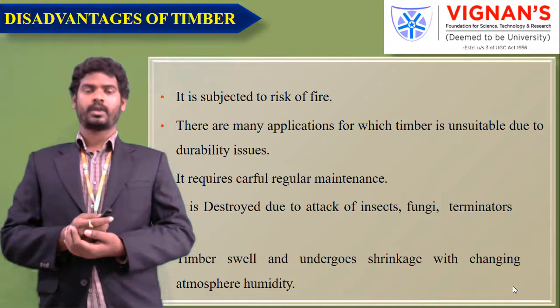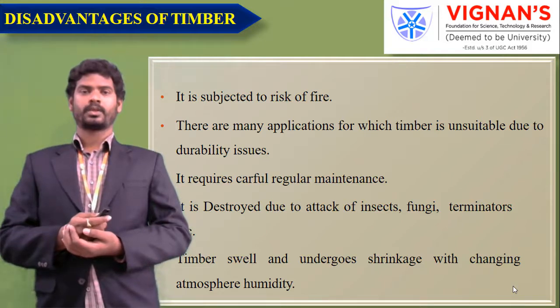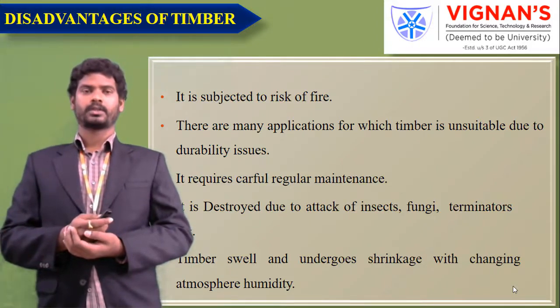It is easily attacked by insects, and that's why damage easily takes place. There are many applications for which timber is unsuitable due to durability issues. Timber swells and undergoes shrinkage with changing atmospheric humidity. Due to changing atmospheric conditions, some shrinkage problems will take place.